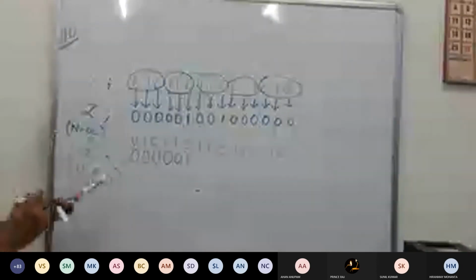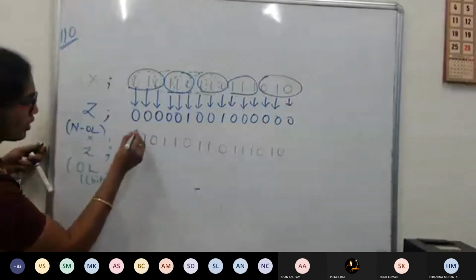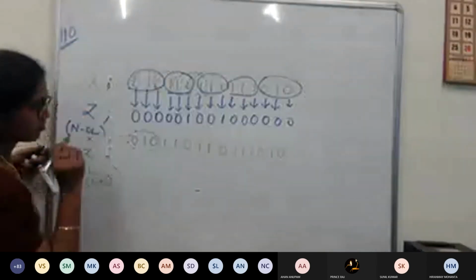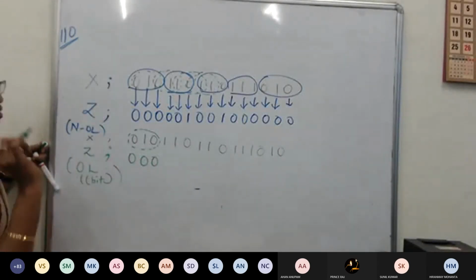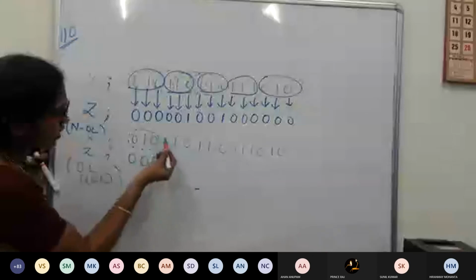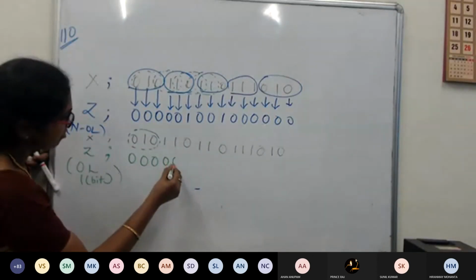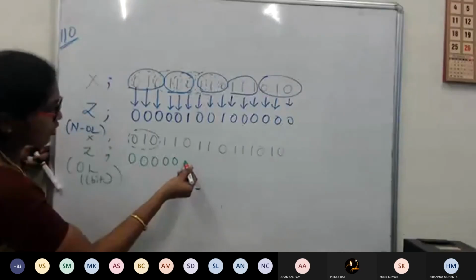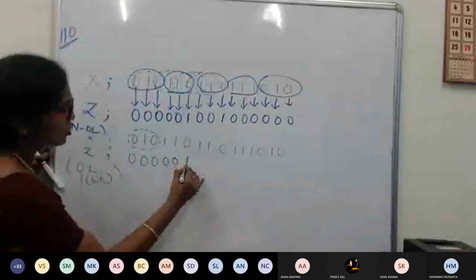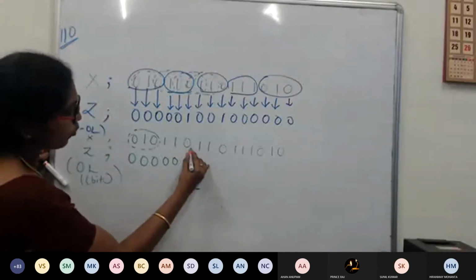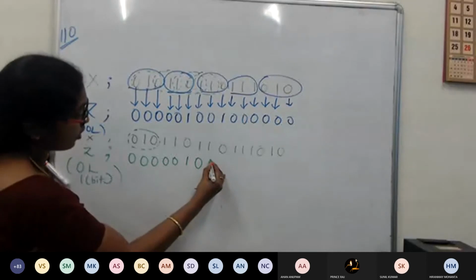Allow 1 bit overlap. Okay, again I will write. So the first sequence is till here. Clearly this is this, because my sequence is 1, 1, 0. The next one is this one acting as this. So 0, 1, 1: no. Then afterwards, this particular one. At this point, it is looking at 1, 1, 0, so it is 1 here. At this point, it is looking at 1, 0, 1, which is 0. At this point, it is looking at 0, 1, 1, which is 0.